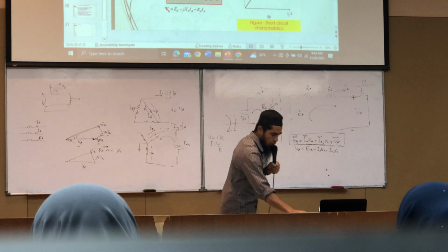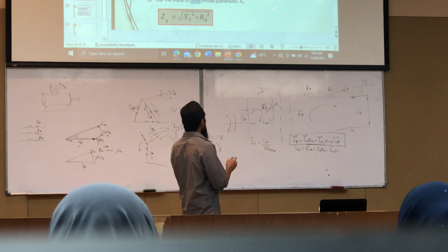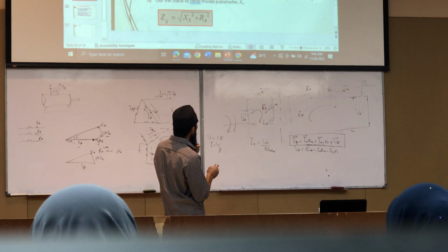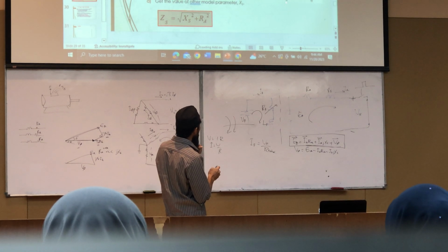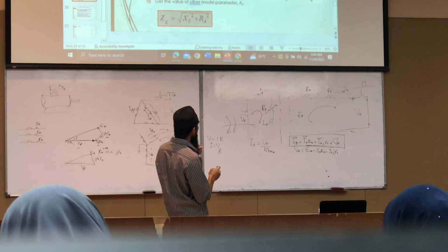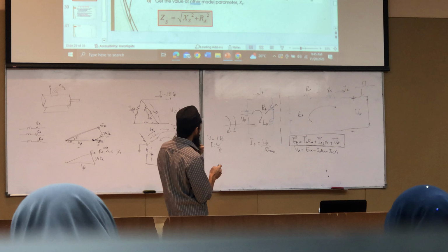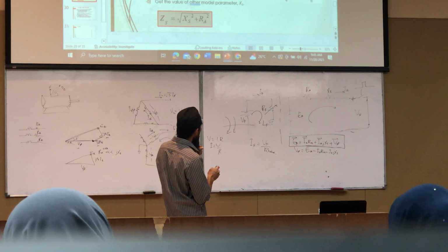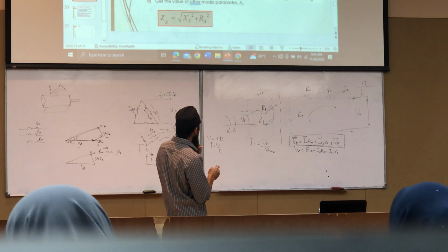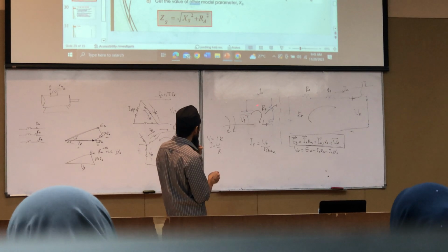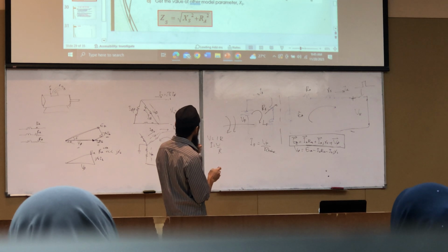So when you have these two parts, you just overlap the results to get how much the rated current of this system is, to get your rated field current here, the rated field current that you're supposed to set. We can test up to how much it can go, and at this time you want to find the rated field current, how much we can increase this to remain in the safe region of the system.